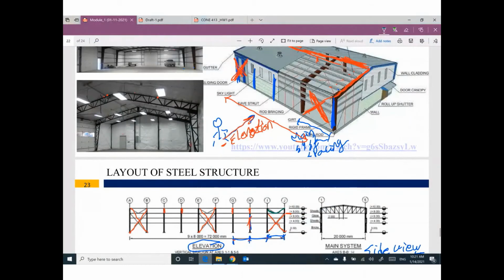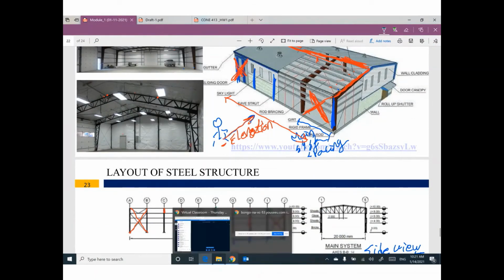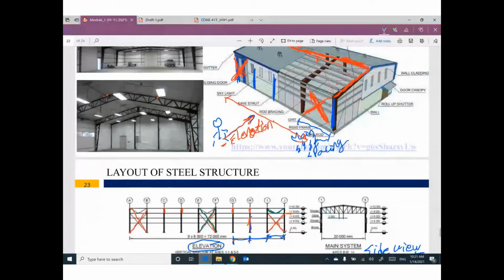I think it's okay. No problem. We don't have an issue with one cross like this. The only issue is if this height is too high. Then this one cross will be too long for this member and this member. We have a concern about buckling because one of them is under tension and one of them is under compression. Anyway, this is the elevation. What about the plan?